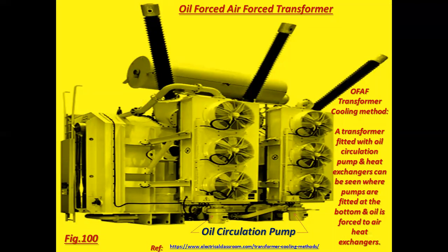Oil forced air forced transformer, physically, say OFAF transformer cooling method. A transformer fitted with oil circulation pump and heat exchangers can be seen, where pumps are fitted at the bottom and oil is forced to air heat exchangers.